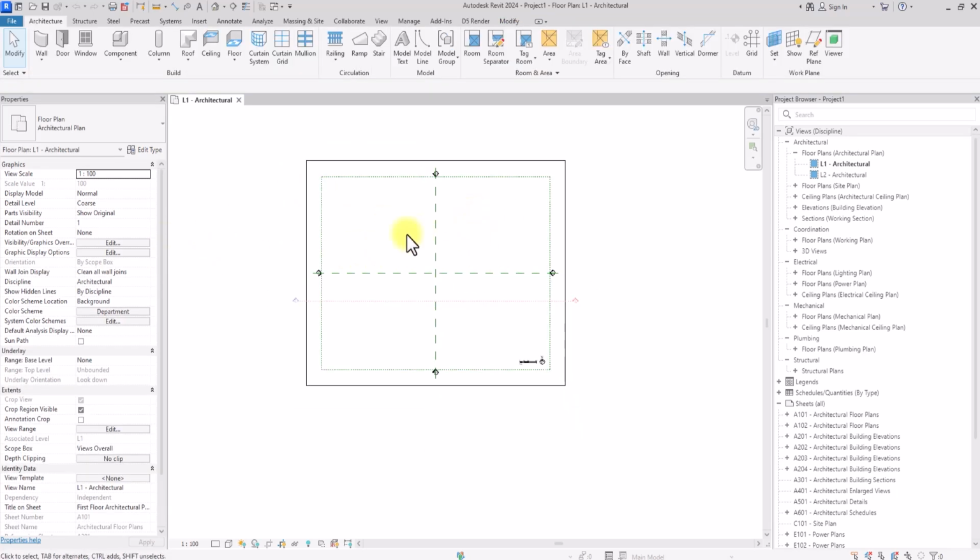The first thing we're going to do once we open a new project in Revit is to create some levels. So what are levels? Levels are vertical reference points. What do I mean by vertical reference points? In a building, you have a lot of vertical points like the first floor, the ceiling, the roof, the lintels, the doors. All those heights are constraints. So we use levels as guides to help us know the position or the distance between all of these heights. To create a level, we are firstly going to go to an elevation view.